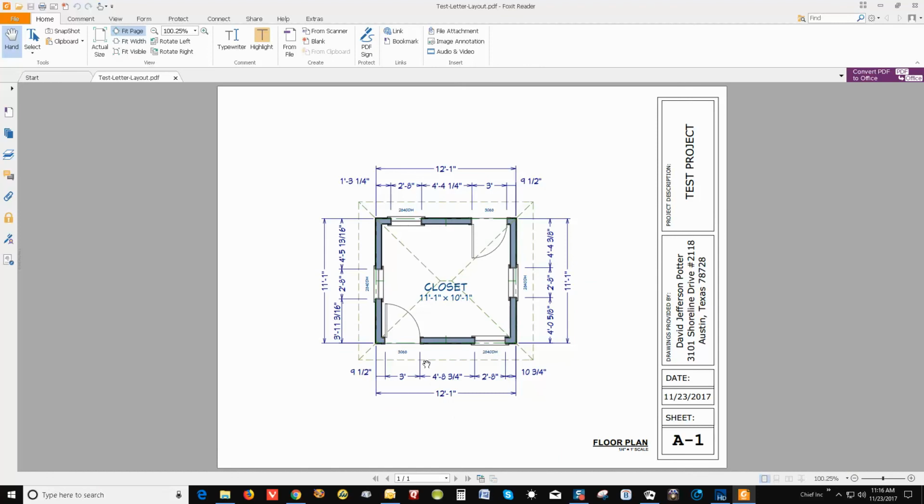And if you were to print this to paper, well, you could put a ruler on there and read it at 1/4 inch scale, that's 12 feet 1 inches. But this will only print the scale if you make sure that all the correct manual settings are right. There are not that many settings, but if you miss one of them, or you assume this is going to go somewhere else on your hard drive, well, then you just wasted some time. So when you do this, be alert and look at each dialog and make sure that the dialogs are set properly for what you intend to have as a product.